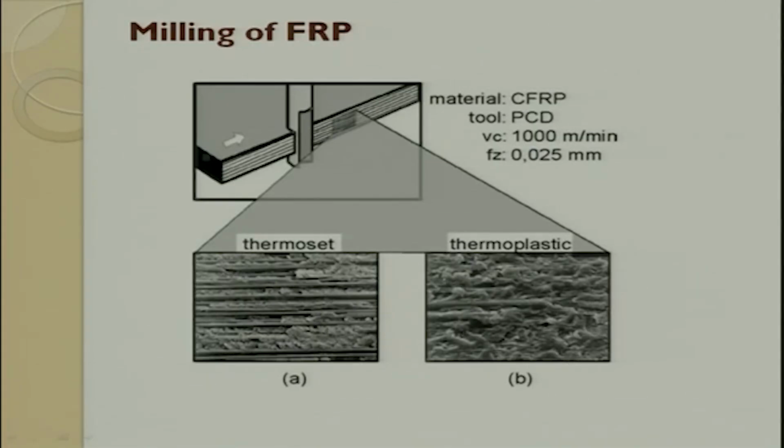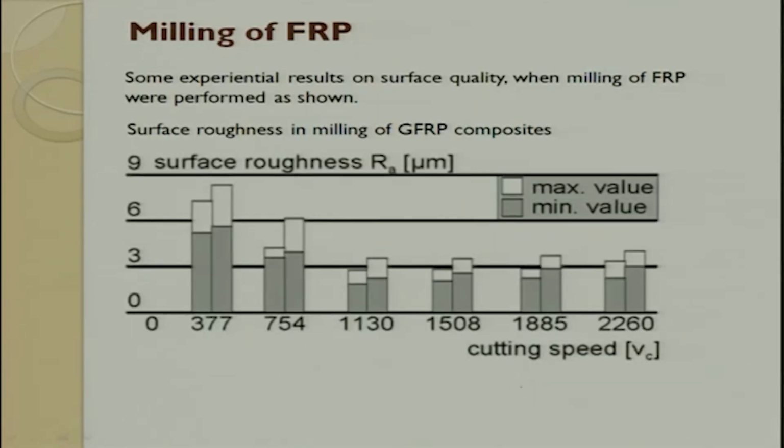This is because of the recyclability property. If you look at the microstructure, cross linking is very high here and very low here. Because of that, after the cutting is over, the polymer tries to distort and brings in roughness. This figure clearly shows the difference in the signature after cutting a thermoset and a thermoplastic. So, this leads to roughness. Here you see the roughness variation between the two; these are the values for milling.